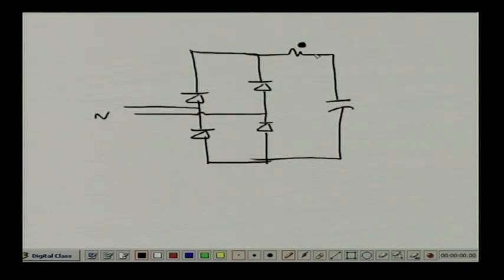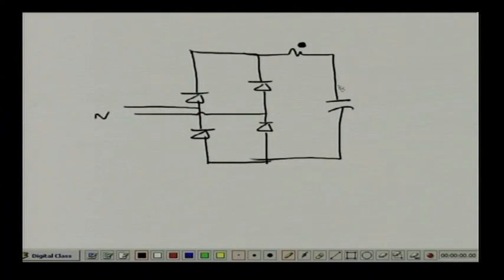A semiconductor device, you can say, sir, I will use some fuse here. But a semiconductor device is to be protected by another semiconductor device, please note that. You cannot do that thing. So I have to use this, and it will offer a large resistance. Slowly it will start to charge, and as the current passes, the temperature rises and the resistance will decrease, so the loss within this thermistor also will be reduced, because this is a total loss.